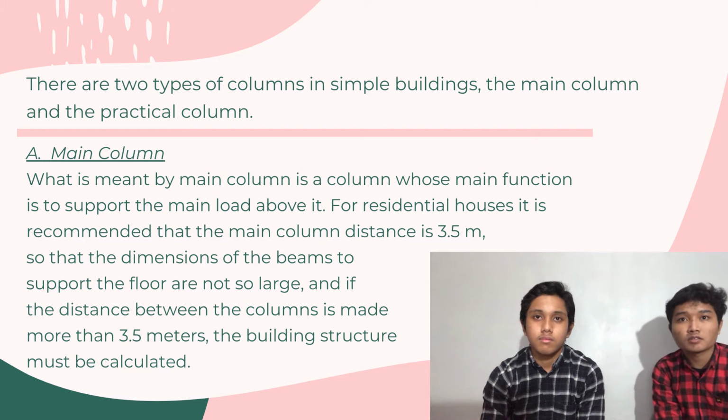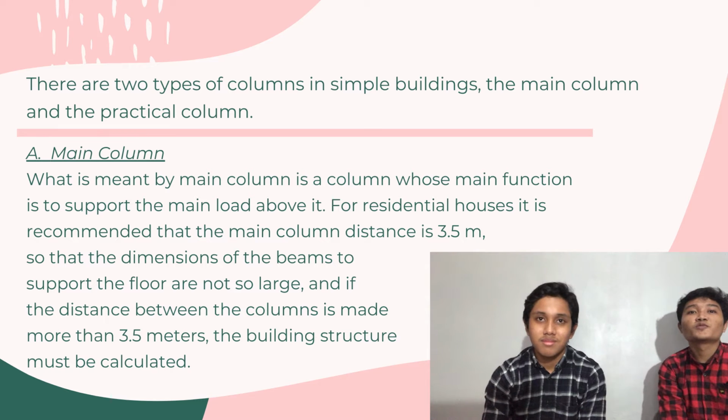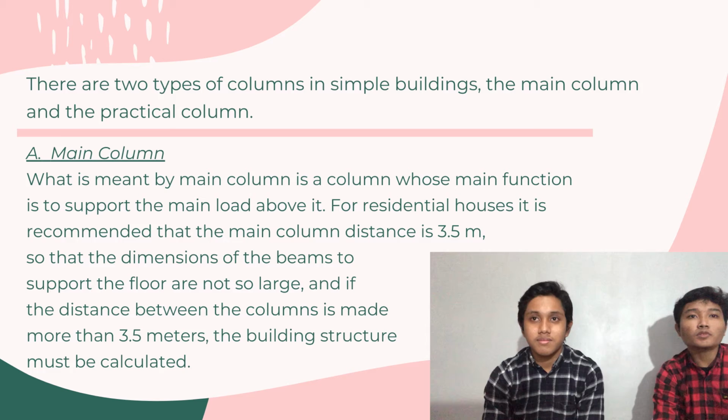When the distance between the columns is made more than 3.5 meters, the building structure must be calculated.